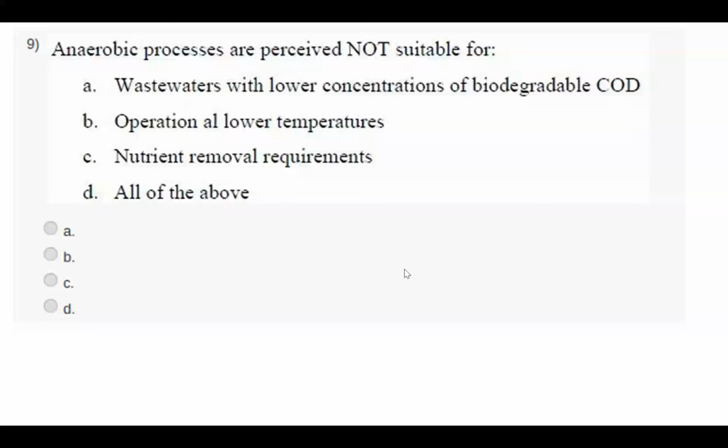A, wastewater with lower concentration of biodegradable COD; B, operational lower temperature; C, nutrient removal requirements; D, all of the above. Yes, all of the above. In these situations, anaerobic processes are perceived as not suitable.